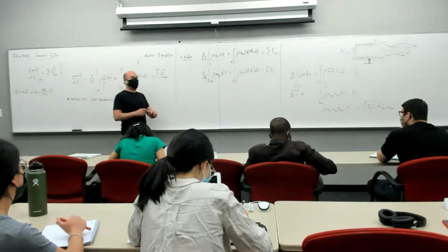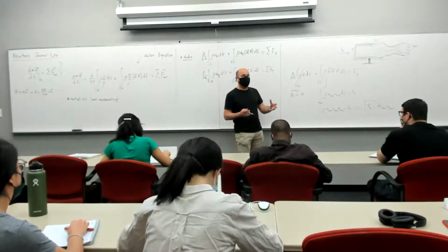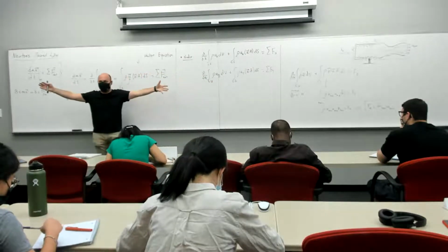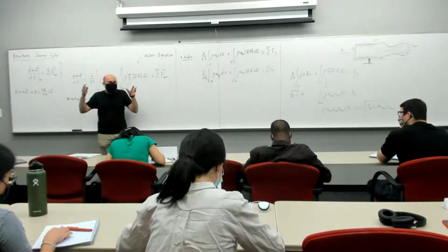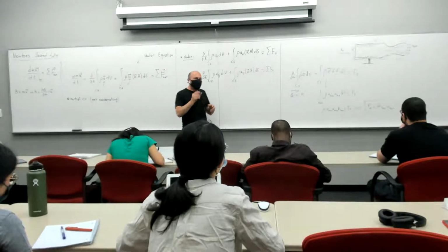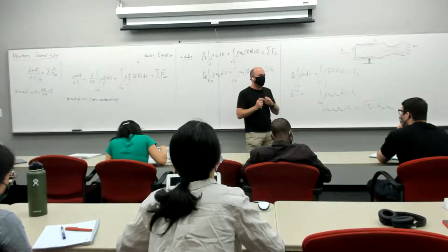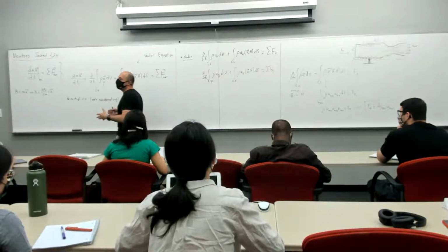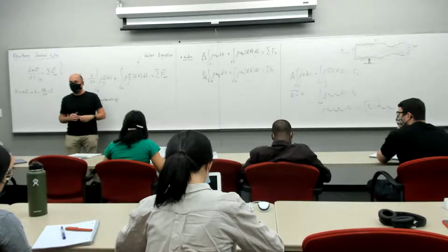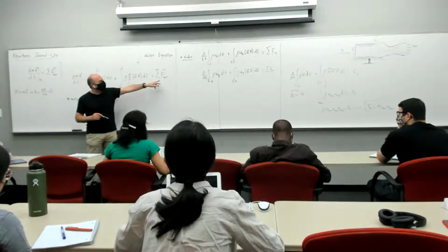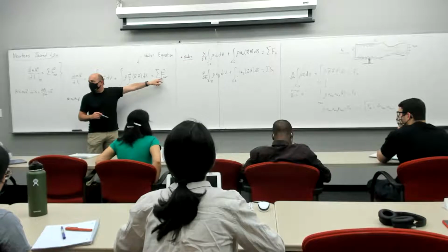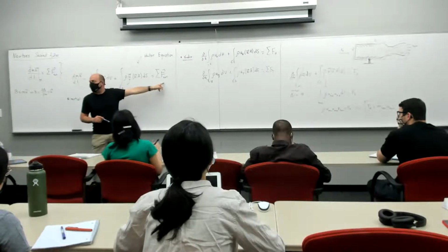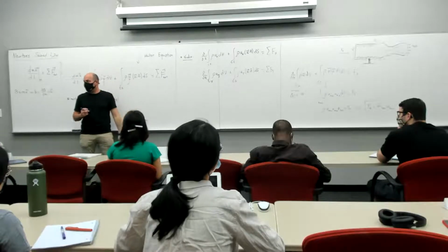So the integral form of the momentum equations helps you in determining really the external forces, in this case on large systems. But once we go inside the fluid, we're going to look at different external forces on the control volume. Once we go to an infinitesimal control volume, that's where the differential form becomes extremely useful. But with the integral form, you rarely know the external forces. Instead, you're using the left-hand side to determine the external forces, okay?